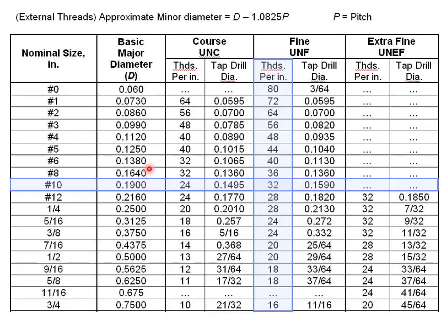Okay, in the back of your book, in the index area, there's this table, and this table is for threads involving inches. I don't have the entire table here. There's some rows missing with larger diameters. Okay, so let's take a look at ½ inch. So if your boss tells you to order ½ inch threads, they're referring to 1/2 is equal to 0.50 inches, and that's your major diameter for the threads. If we order quarter, 1/4, that's 0.25 inches for your major diameter.